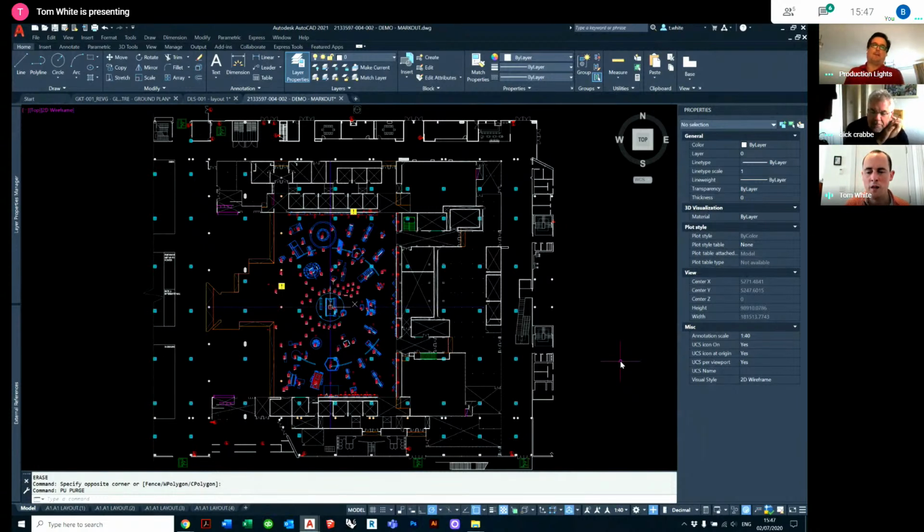And Dom, I think it's a relatively safe thing to do, because if you're able to purge it, it means that it's not visually represented. So you could go to the blocks and say block number 335 is there, but it's not inserted anywhere. So as the end user, I don't know where it should be inserted. So whoever produced the drawing has deleted block number 335. So it's totally safe. In comparison to another tool that you can use, which is not safe, called overkill.